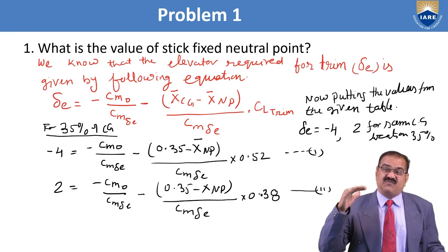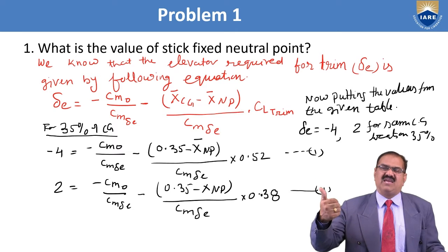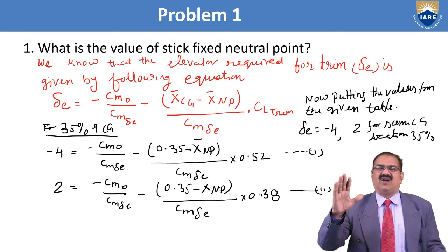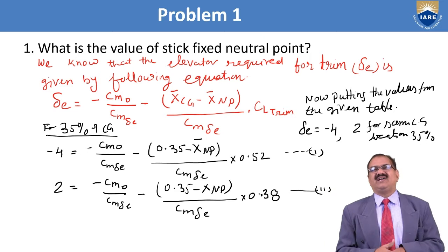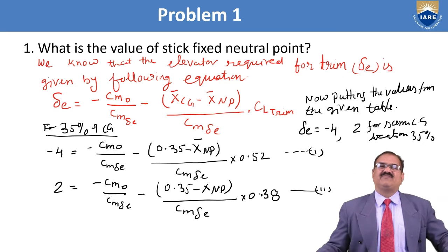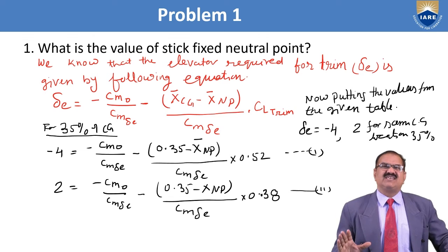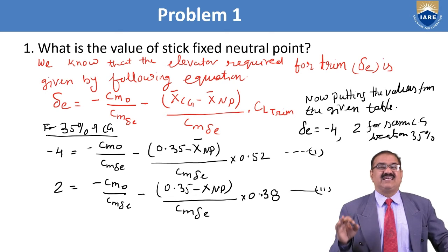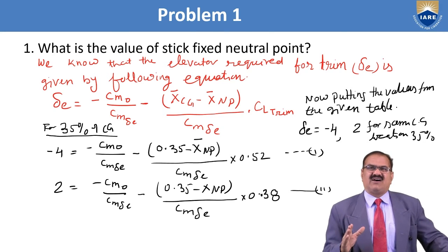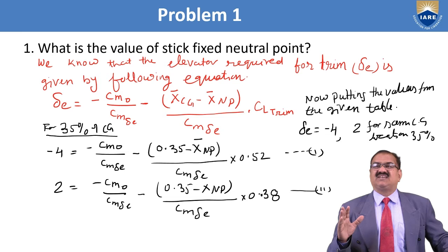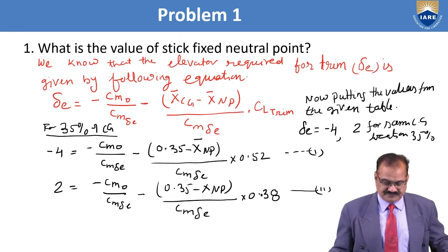But if it is free, it means there is aerodynamic effect or further variation on the position of the stick or position of the control surfaces. So that is the difference. Here we are not considering stick free. All the equations are solved using the stick fixed condition only.